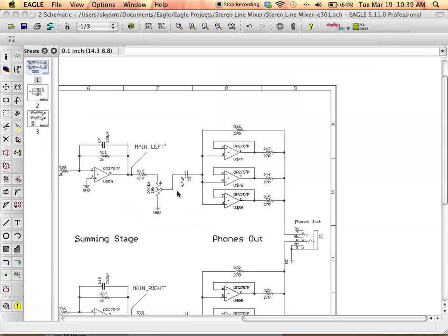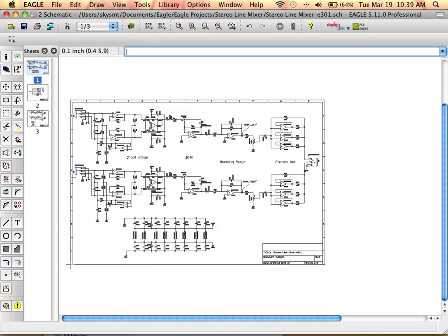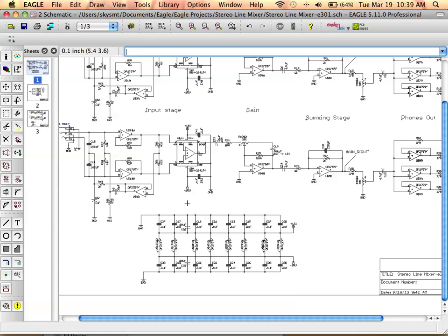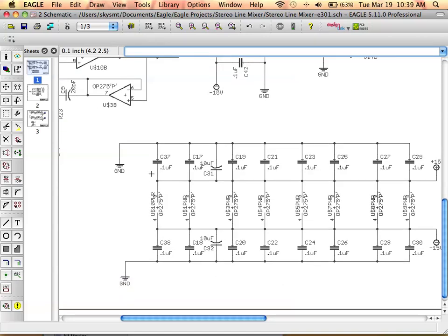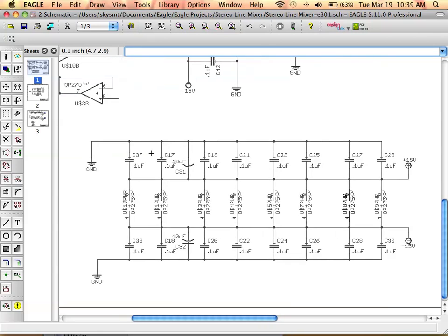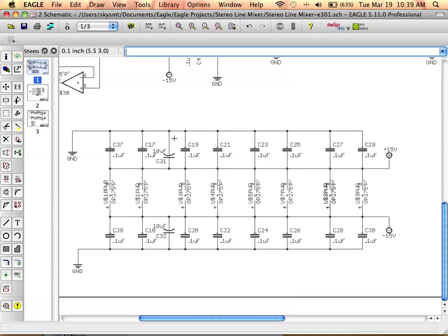Well, those are the bypass capacitors. Starting with the BJT lab, we'll start looking at the use of bypass capacitors. Has anyone ever heard of using that before, or a little bit here and there? They're capacitors that are intended to locally stabilize the power supply levels at ICs. So in general, you typically place these just next to the power supply pins on the ICs.